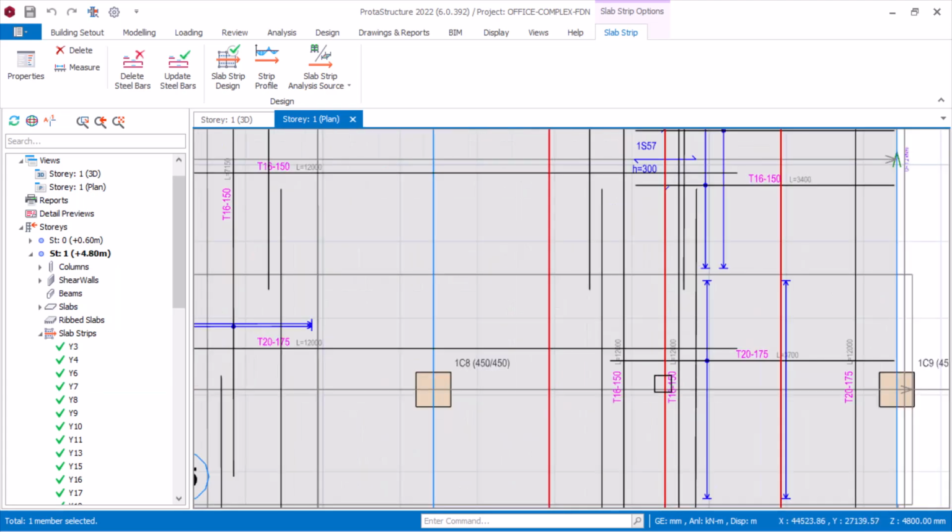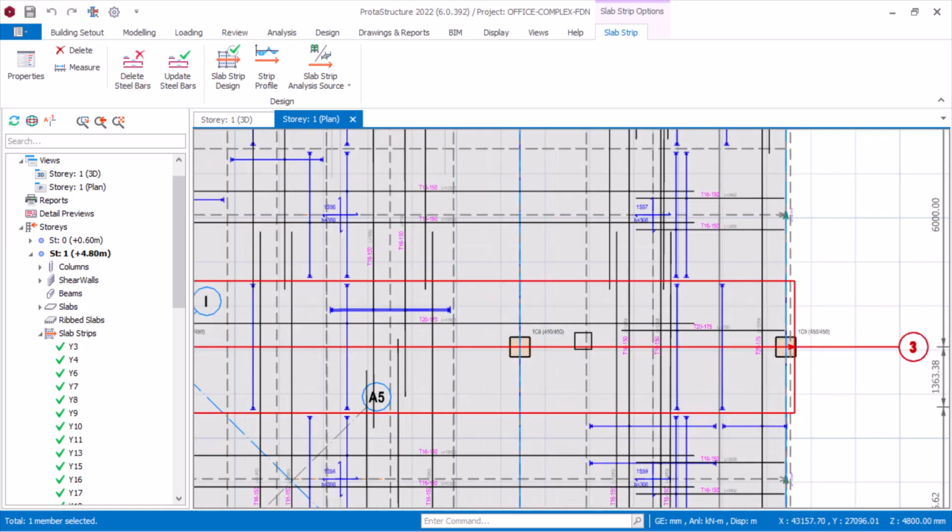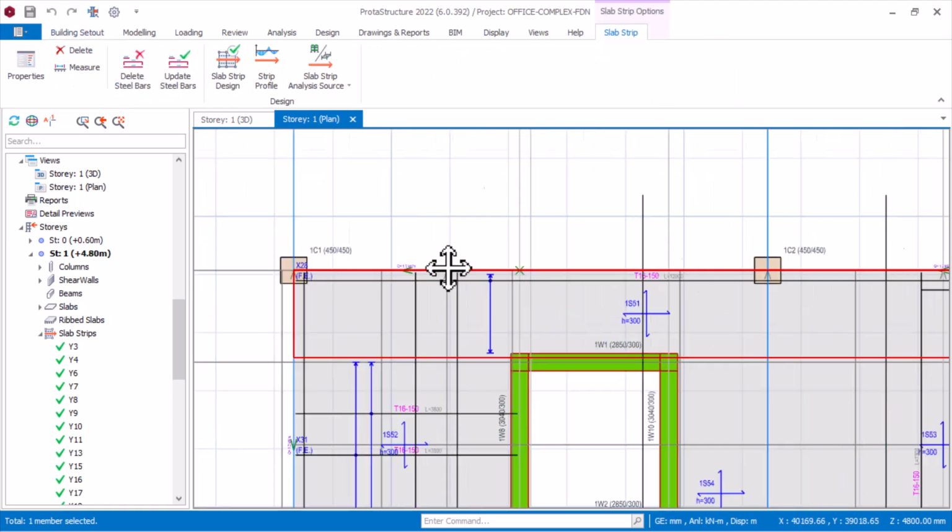So you can see, after you're done with your normal design for the slab, the normal design will give you the minimal reinforcement top and bottom for the slab generally. Then around each of the columns, you now calculate for punching, which gives you the punching zone or the punching region. When you have known the punching region, you now design for the punching reinforcement.